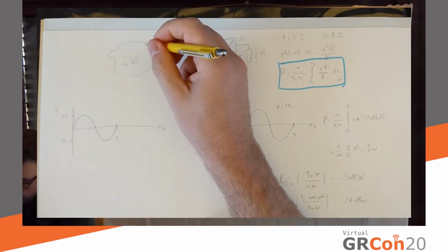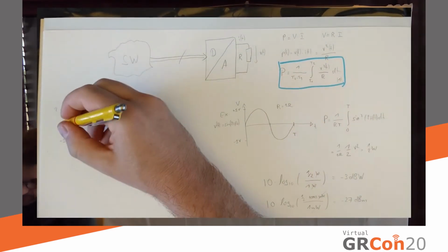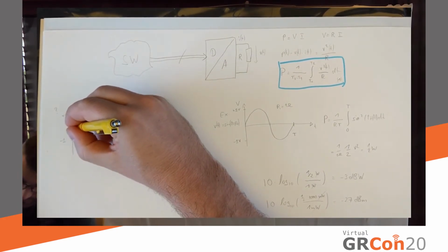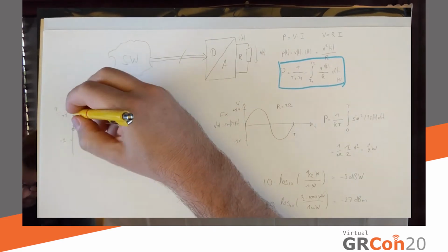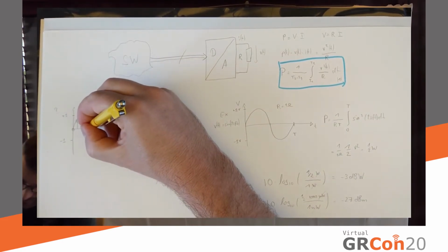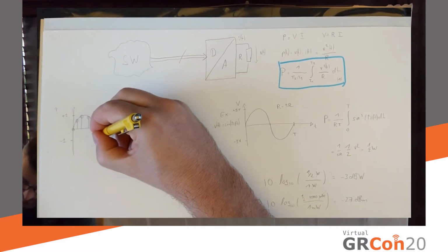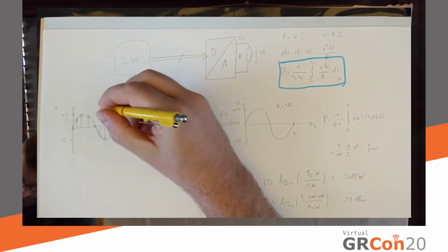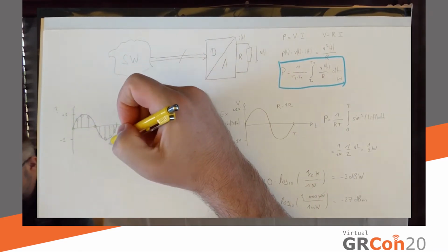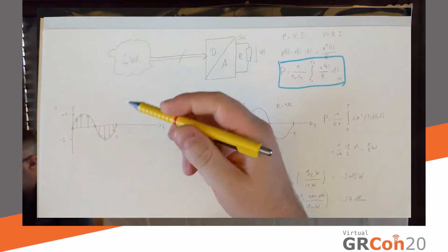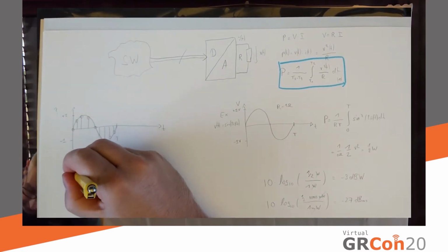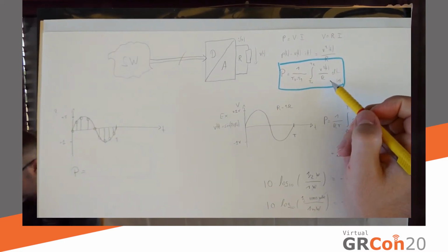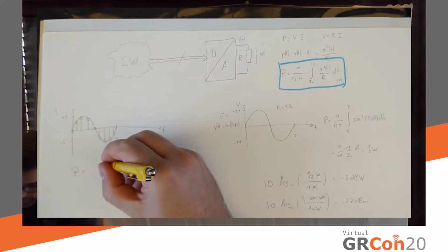The other thing that's important in software is we don't have an analog quantity here. Rather, we are sampling this. So the sine wave I drew is fake, does not exist in software. What we do have are these sample values that I'm trying to draw equidistantly, unsuccessfully. 4 of them. So these 8 numbers here represent my sine wave. If I want to calculate the power of that, then I'm going to copy this equation because it's still useful, except I'm going to have to modify it.